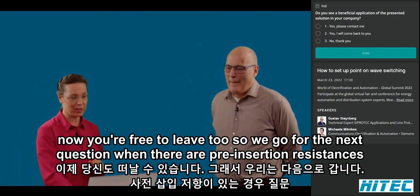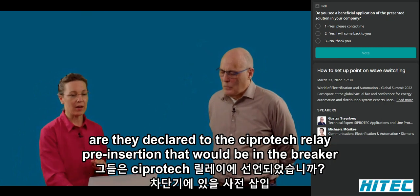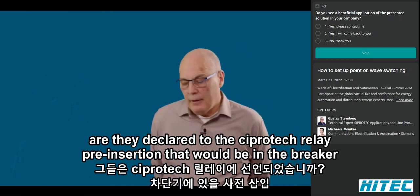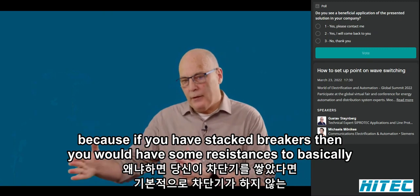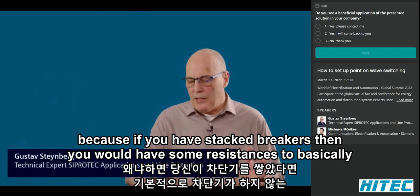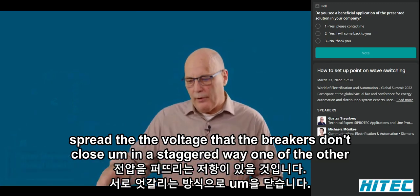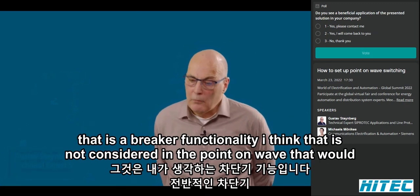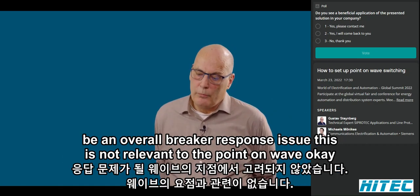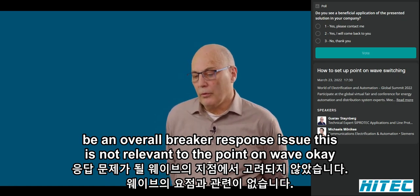So we go for the next question. When there are pre-insertion resistances, are they declared to the SIPROTEC relay? Pre-insertion, that would be in the breaker, because if you have stacked breakers, then you would have some resistances to basically spread the voltage, so that the breakers don't close in a staggered way, one after the other. That is a breaker functionality. I think that is not considered in the point-on-wave. That would be an overall breaker response issue. This is not relevant to the point-on-wave.